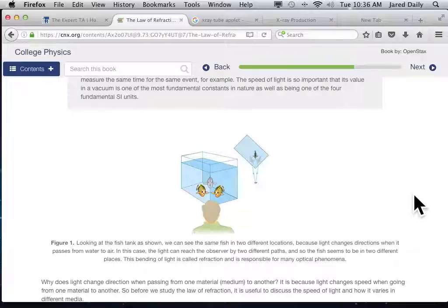Anyway, the point is that it's stupid to put those in the middle of the road. It's stupid. And because it pulls you in, now why does it pull you in? Here's the big question today. What is causing that pulling you in? What are those rumble bars? What does the sand or the gravel do to one side of the vehicle that it's not doing to the other side of the vehicle? It adds friction, which does what to that side? Slows it down. So one side is slowing down while the other one keeps going. That turns things, doesn't it? So it's going to turn you towards the rumble bars, towards the sand, towards the gravel.